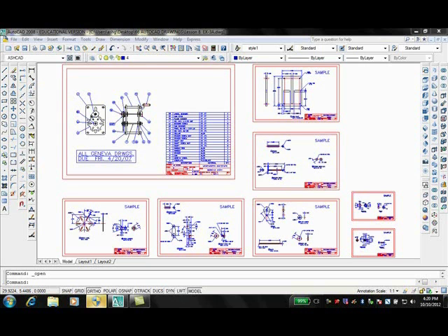Regardless of the scale of a printed drawing, when drawings are printed in either model or paper space, they have to be consistent. All companies want text and text height to be standard sizes. Out of necessity, there have to be changes to the variables of DIMSCALE and LTSCALE.